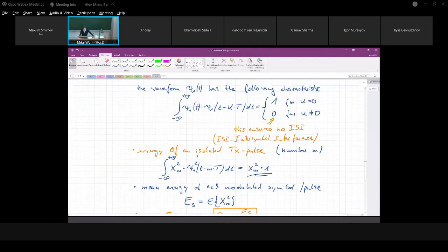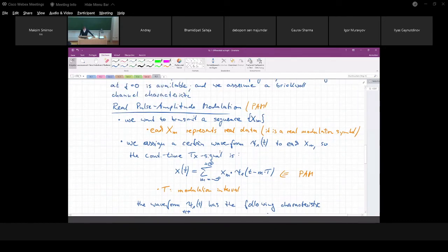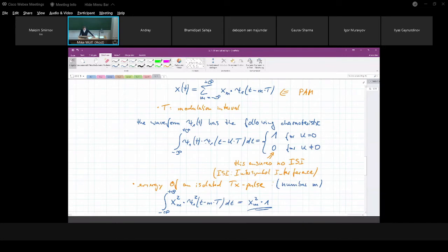So, if we would write down the convolution of the transmit signal with this matched filter impulse response, we end up basically in parts of this convolution which look like this, because let's say we transmit a pulse at the time, this is the pulse train, then we could insert here m, and this is the matched filter impulse response.